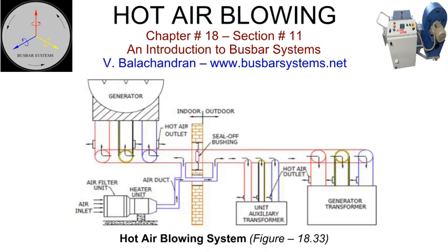In the case of an isolated phase bus, the hot air is fed approximately in the middle section of the length. The outlet can be at the end of the bus connection. Moisture condensation on seal-off bushings installed at the station wall and at terminating ends will be most susceptible to the fall in the insulation level of the conductor. Such locations will need special attention.